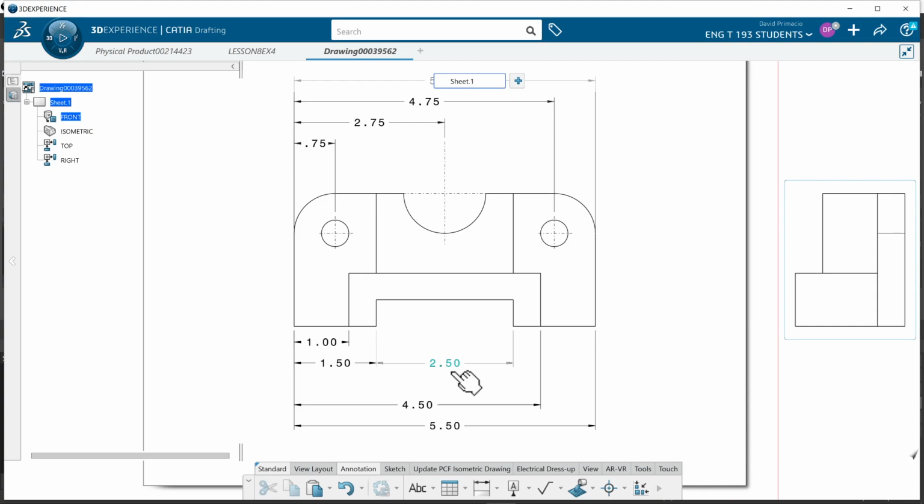Whereas before, the other way I dimensioned it, the smallest it could be is 2.44. Again, that has to do everything with engineering tolerance. If we were using plus or minus 30 thou, that's 0.030, 30 thousandths of an inch, then this dimension will go to this, the minimum number would be 2.47 and the maximum number would be 2.53.